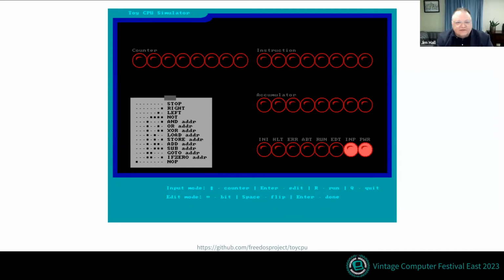And there's a NOP instruction there as well, which technically any instruction that is not recognized is also the same as a NOP, although you have to be very careful because you'll notice that the 4th bit in from the left has been set for any instruction that also pulls data from memory. So you have to be very careful if you have something that you mean to be a NOP instruction that also sets that bit, because that can actually cause your program to have a quite serious bug. It'll advance the counter.